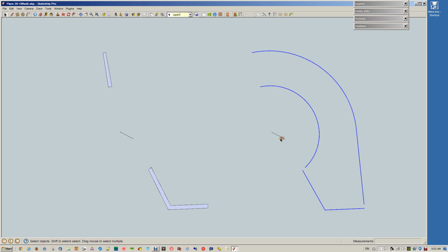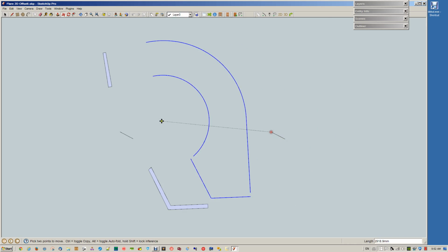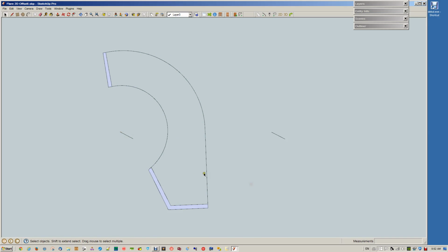And we're going to move these back into place. Now this should complete. There we go. Okay, now that we've got this, again, if I remove this, it's going to create a, no, it shouldn't now. Now that we've glued these edges together and it's part of a curve, SketchUp won't join these together. It leaves these separated, which is what we're looking for. So we can get rid of these now too.